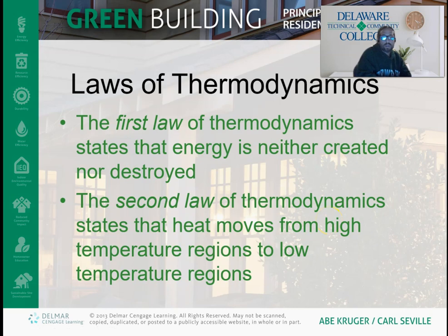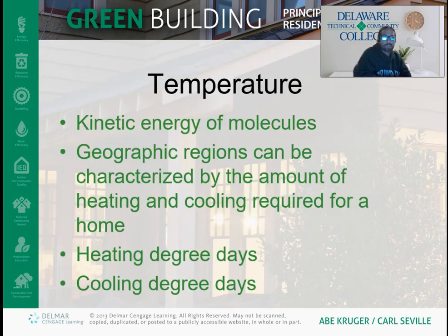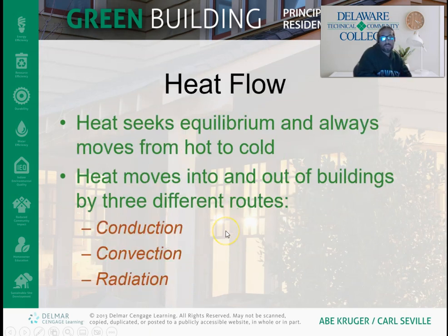All of these apply in a lot of different ways to energy and other systems in buildings. So remember, we've talked about temperature being the average kinetic energy of molecules of a substance. We have discussed heating degree days. We haven't really discussed cooling degree days, but think of them as the opposite of heating degree days. Remember, heating degree days are generally how much heating you need, how cold the climate is. Cooling degree days are just the opposite. If you have a lot of cooling degree days, that means you have a pretty warm climate and you need a lot of cooling. The maps of those two, HDD and CDD, would be pretty opposite, and they would roughly match up to the climate zones.